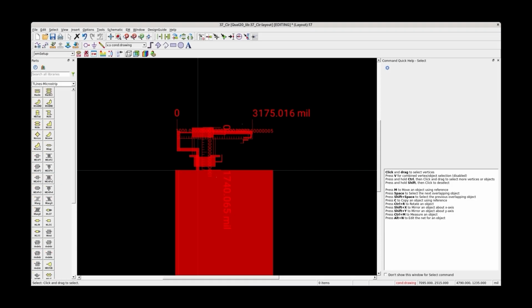We will move on to our step 4, which is EM simulation. We will be using RF Pro to do EM simulation. RF Pro is a new EM simulation software that comes with ADS. We will double check our return loss optimized using EM setup and also simulate far field parameters such as gain, efficiency, radiation pattern using RF Pro.